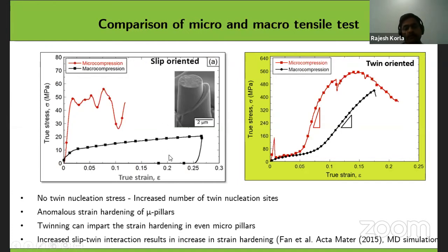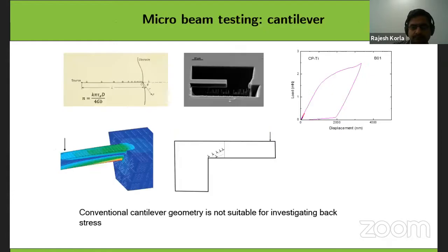So the same pure magnesium, in one orientation, you're seeing one behavior. Another orientation shows different behavior. So it itself suggests that material anisotropy and material orientation play a significant role in the deformation behavior. If the polycrystal is randomly oriented, you can do deformation in a particular direction, and it's fine. But if it is a single crystal or highly oriented grains, then you definitely have to probe the mechanical properties in different directions to see whether anisotropy exists or not.